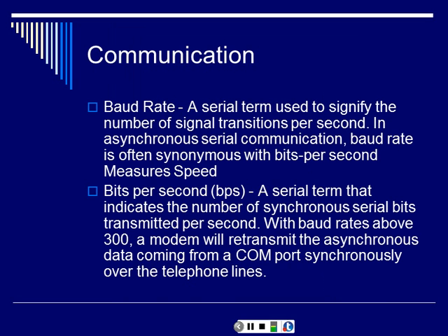Okay, I'm not really going to cover this too much. Is it still in your book? The baud rate? Okay. Baud rate is actually an old serial term. It really means the same thing as BPS, which is bits per second. It indicates how many binary digits can be transferred from one place to another in 1 second. So not bytes. It is bits per second.